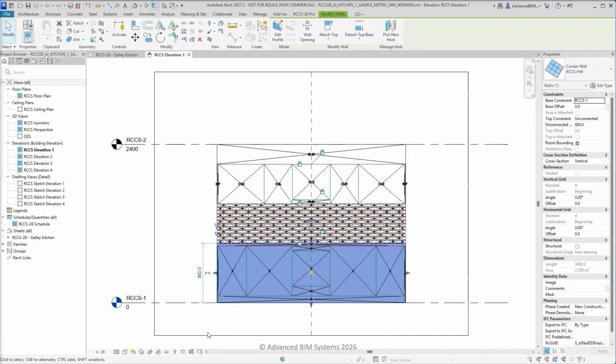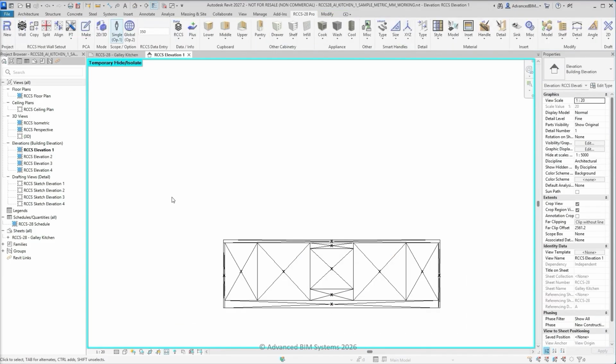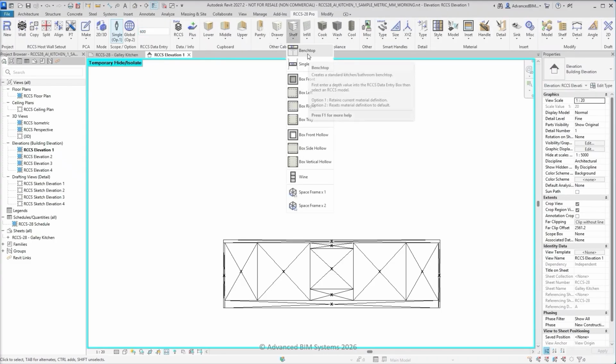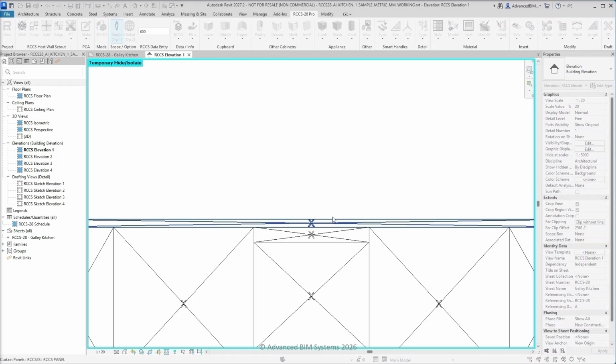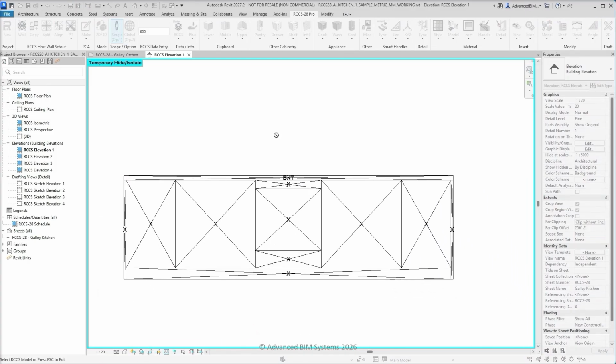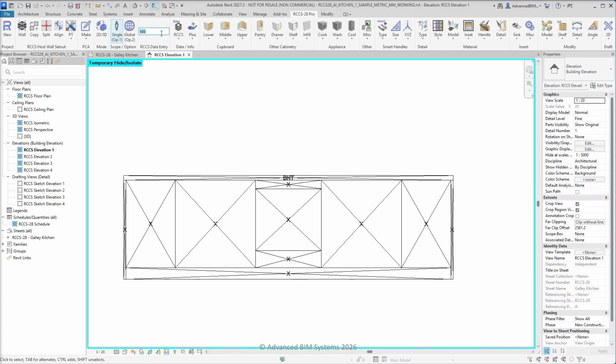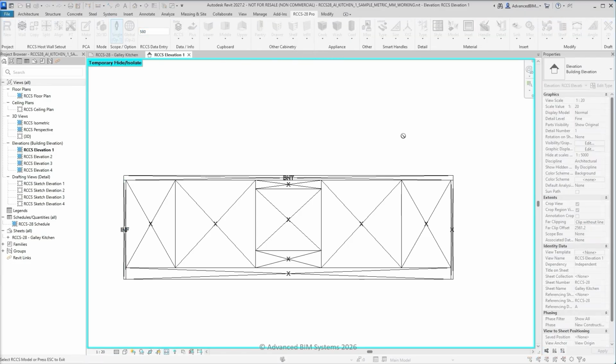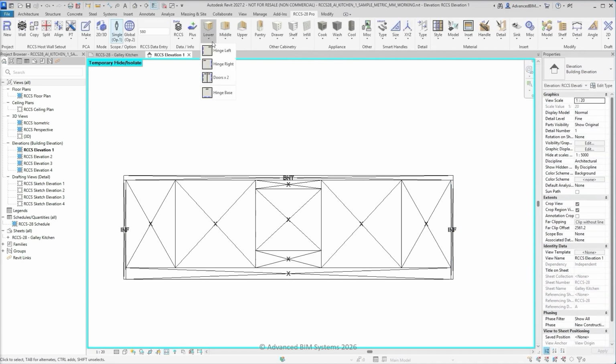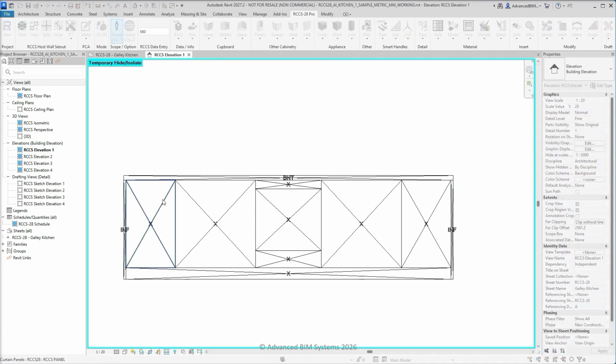Repeat the same process to assign cabinetry types to the base cabinet panels, while changing the depth value when it's required. It's good practice to assign the cabinetry types with the same depth value sequentially, and only change the depth value for individual components when needed.